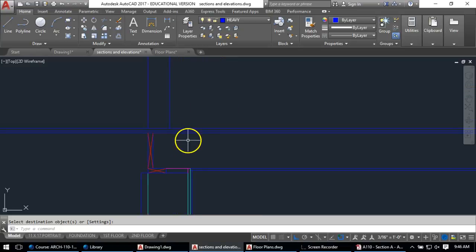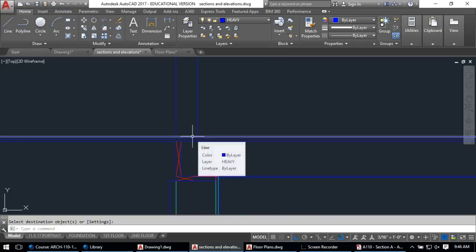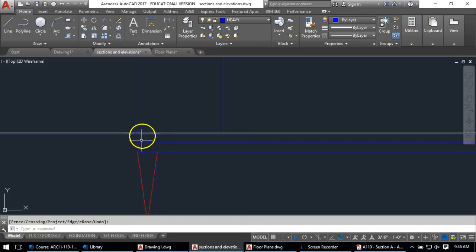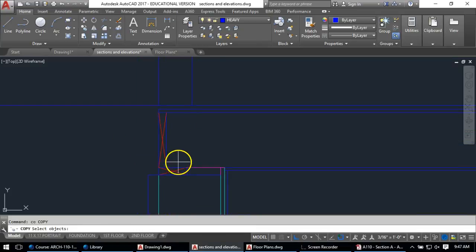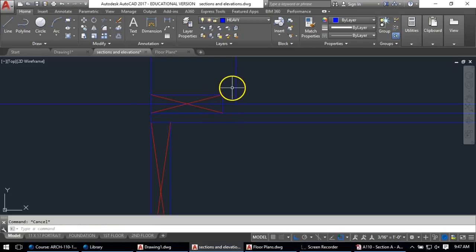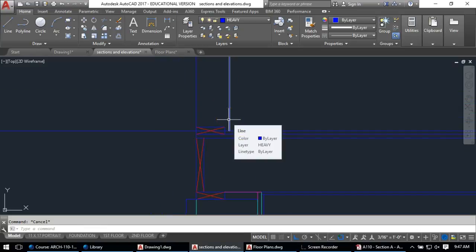All right. So I've got that little section done, and I will draw the next bit here. The way we construct the wall is I'm going to have my subfloor go to this edge location, trim up those lines, but then I'm going to have a 2x6 that sits on top of that, just like this. Okay, and of course on top of that, on this one side, I'm going to have my drywall.